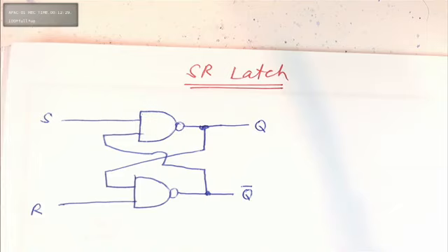Combinational circuits, the moment you change your input, will process the new set of inputs and bring you an output. Sometimes if you have a 16 line truth table, let's do the security problem. If A, B, and C are 0 and D is 1, your output will be 0. And if A is 0, B is 1, C is 1, and D is 0, again your output will be 0. Your input changed, and the answer is the same, still 0 because the majority of inputs were 0. But it did a fresh new calculation to come to the answer 0. It didn't save it in memory and remember that it was 0.